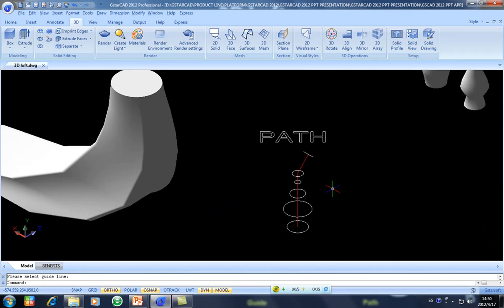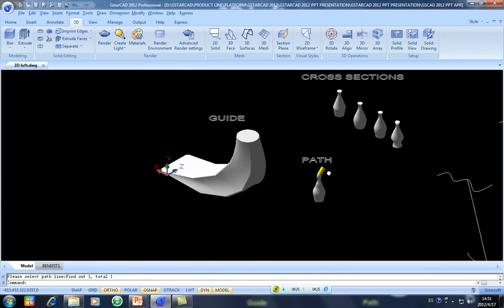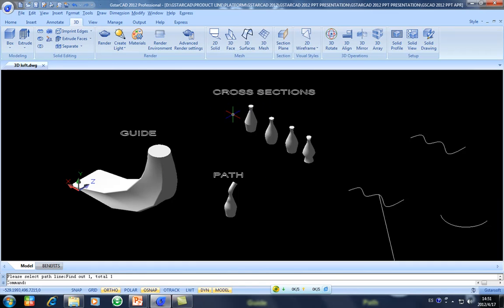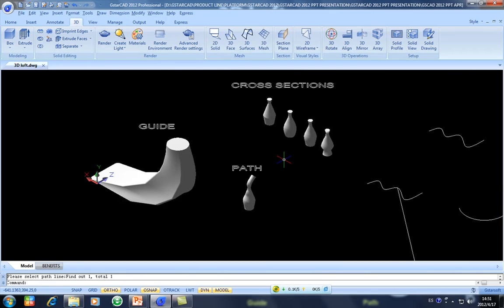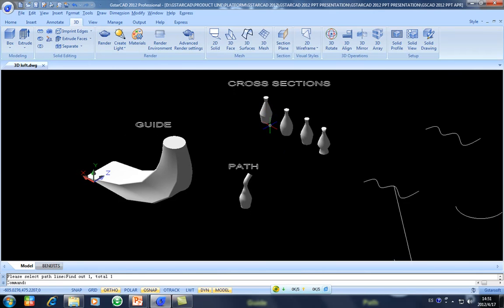Okay, and then I will perform path. So I will do loft here. I will select my cross section around here. Carefully, do not select the center line. I select this, and then I put the option P, that means path, and then I select the center line here, and that's it. Okay, totally different, three different lofting options with different solid effects, because those are closed entities.